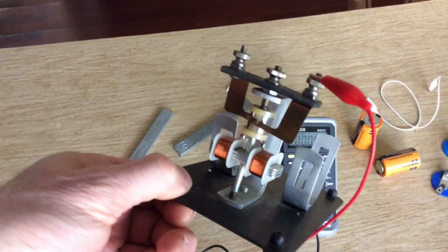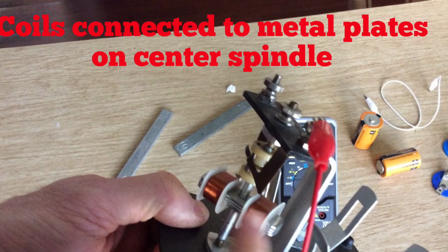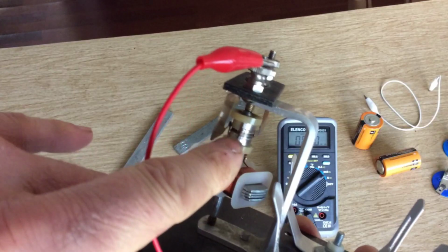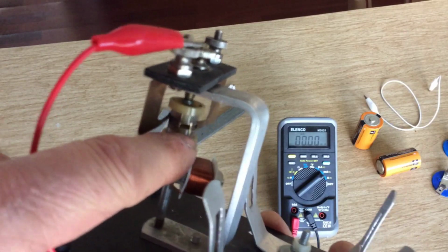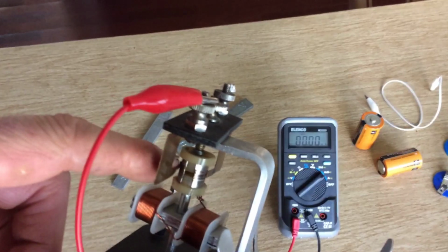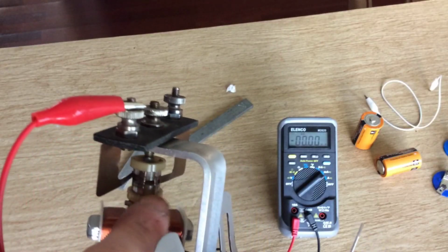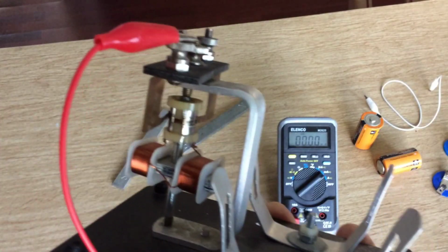Oops, and you can see that these coils are somehow connected to these metal plates on this spindle that spins around. On the spindle itself, there's areas where it's metal, and then there's areas where the metal stops and it becomes plastic. I don't know if you can see that very well. So one of these metal pieces is connected to this brush when it's touching. At that time, the other metal plate on the other side of the spindle is connected with the other brush. These are the brushes of the motor.